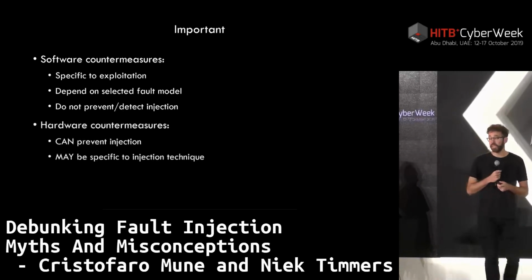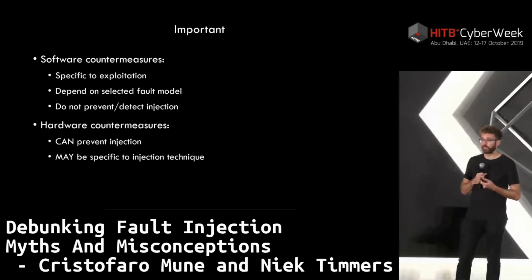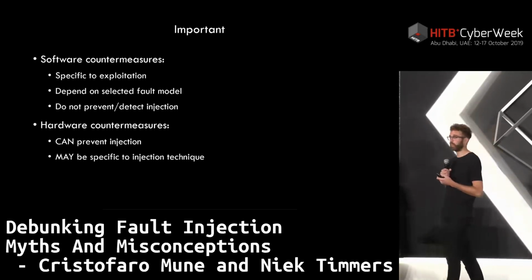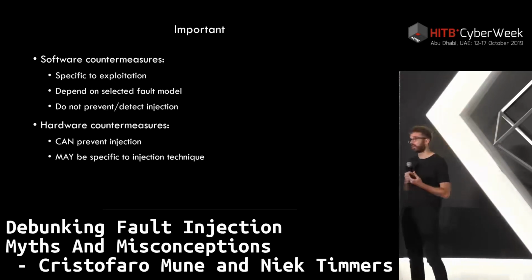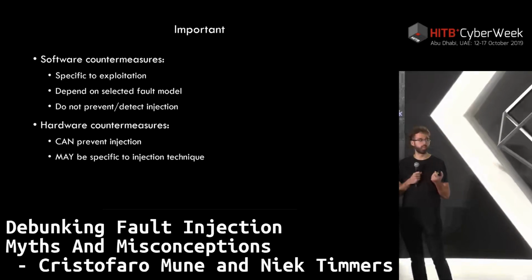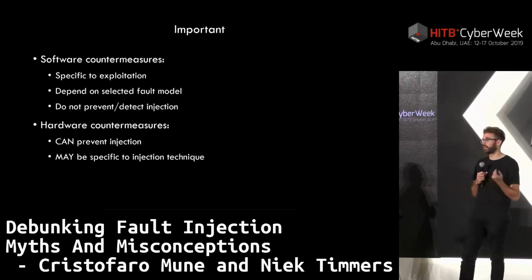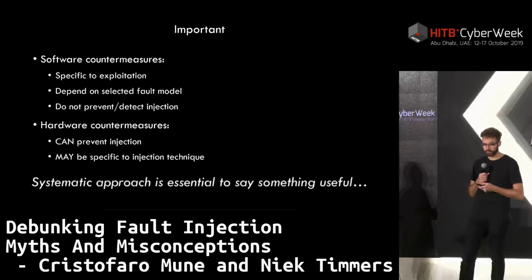Hardware countermeasures can actually prevent the injection technique. And typically these hardware countermeasures are specific to an injection technique, but some hardware countermeasures are also applicable to all injection techniques. For example, ECC RAM: it doesn't matter how you inject the glitch, it will actually work and put some assurances on the data for all the injection techniques.